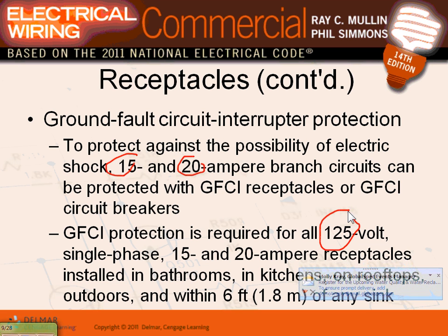By the way, when we deal with a commercial building, forget a 15 amp receptacle. Don't even deal with 15 amp circuits or receptacles. The minimum, on a good engineered project, guys, the minimum branch circuit that you can pull and the minimum receptacle that you can put is a 20 amp receptacle, 120, landing on a 20 amp branch circuit. It's really not worth putting a 15 amp receptacle, if you ask me.